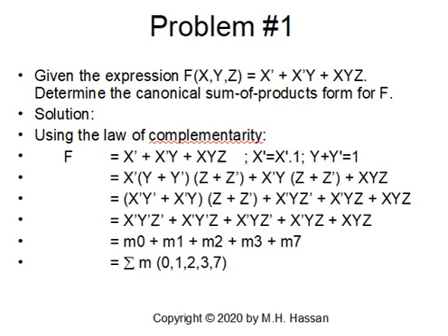The first way is to construct the truth table for the function. Then for every value of the function equal to 1, we look at the corresponding minterm. Then by adding all the minterms, we represent the function f. Or we can use Boolean algebra. To do that, we will look at every term and study it.